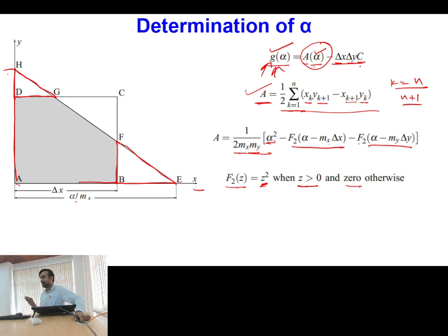So, you can see now that the process of reconstructing the interface is not very simple. And I am explaining all these computations for a single cell. If you have, say, 1 lakh or 5 lakh cells present in one system, then for each and every cell you have to do this computation. And you have to remember one more point: whatever discussion we have done till now is for a structured Cartesian grid. If you go for an unstructured mesh, then the computation will be even more challenging.